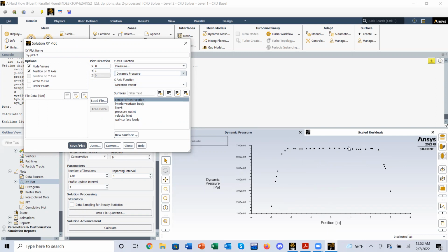We are just measuring the middle of the test section, so you have to remember that the center of the test section is the highest velocity, and so at the bottom is going to be a lower velocity than in the middle of the test section, vertically speaking. It is going to be almost the same velocity, the whole center area, and then as you get to the top of the test section, the roof, the ceiling, it's going to get lower.